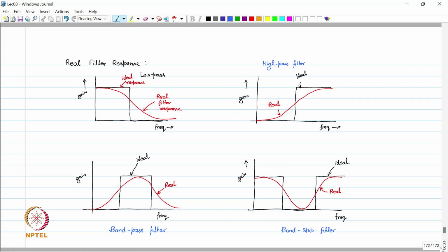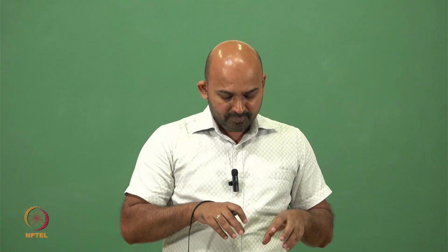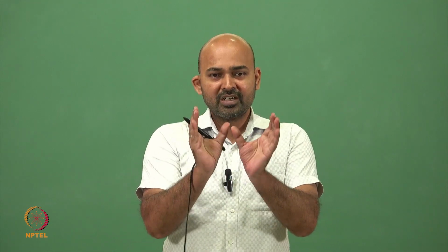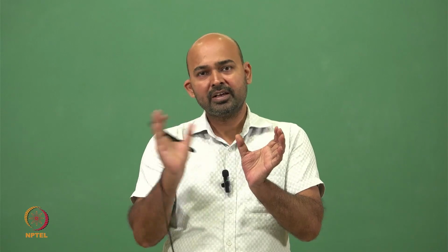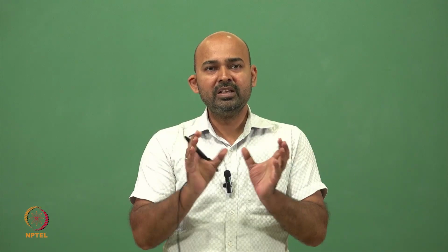So these are the four types of filters generally used for filtering. A low pass filter passes low frequencies and rejects higher ones. A high pass filter removes low frequencies and passes high frequencies. A band pass filter means we have a certain band only that we are interested in; below or above these frequencies, all will be rejected.